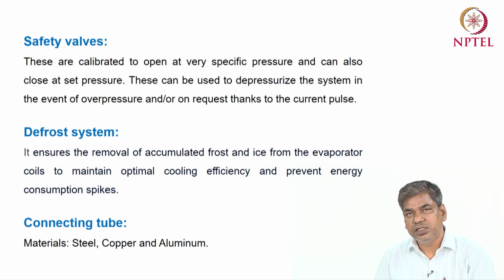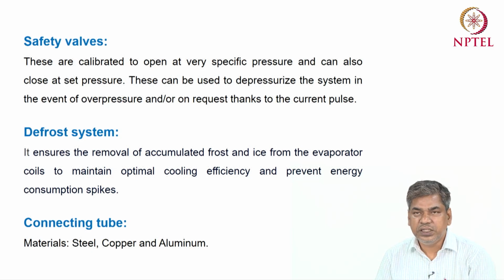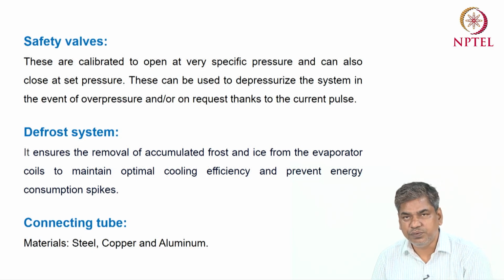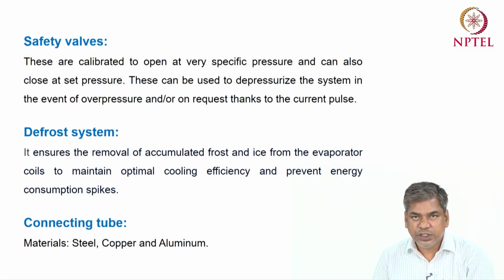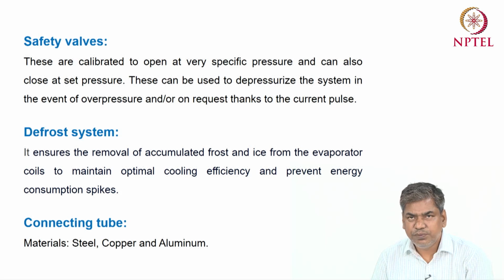So that's why, for safety purposes, on the low side also we have to use a safety valve, which basically stops the system if the pressure is lower than some pre-decided pressure or safe pressure of the system. Okay, so for the high side and low side, safety valves are required on both sides for safe operation of the refrigeration system. Then the defrost system.